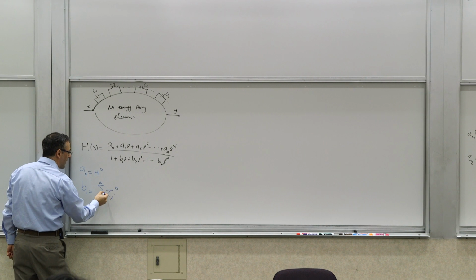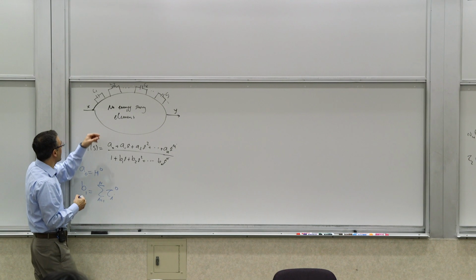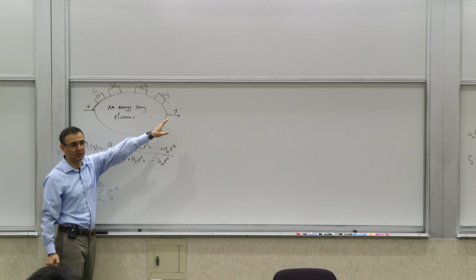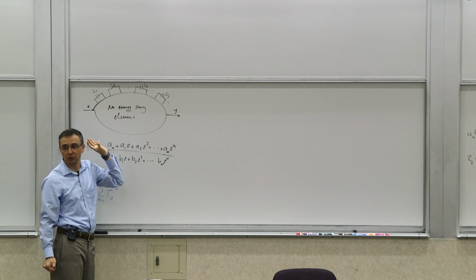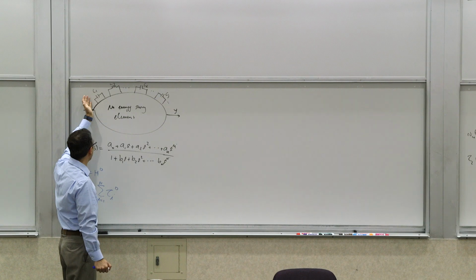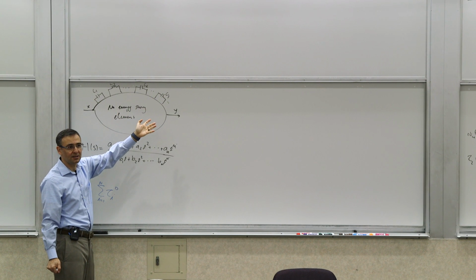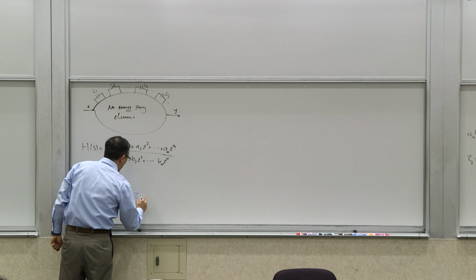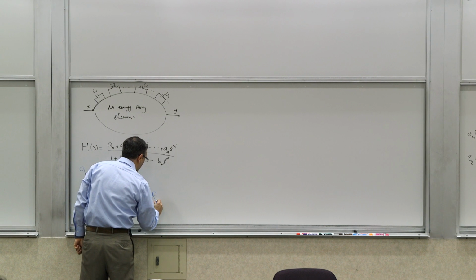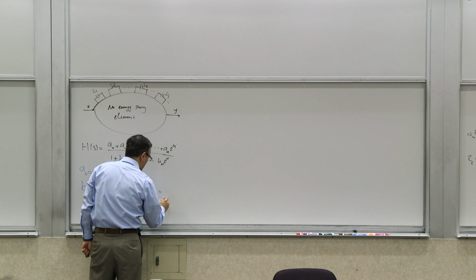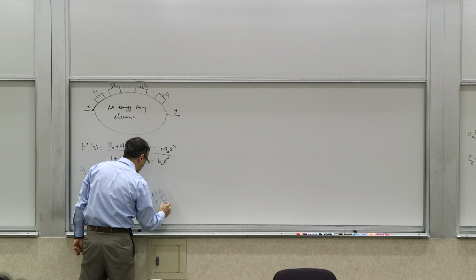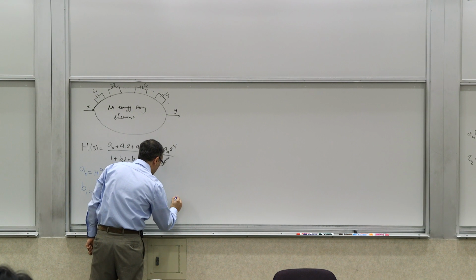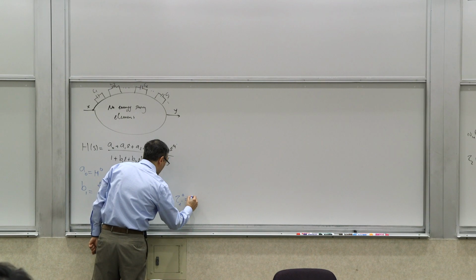So, and what were the zero value time constants? Zero value time constants where you look at the resistance seen by one of these elements where all the other elements are zero valued and all the sources are null, independent sources are null. You look at that resistor. If it's a capacitor, it's that capacitor times that resistance. We call those resistances, so these were either, so where tau_i0 was either R_i0, the resistance seen when all the other elements are zero valued, times Ci,